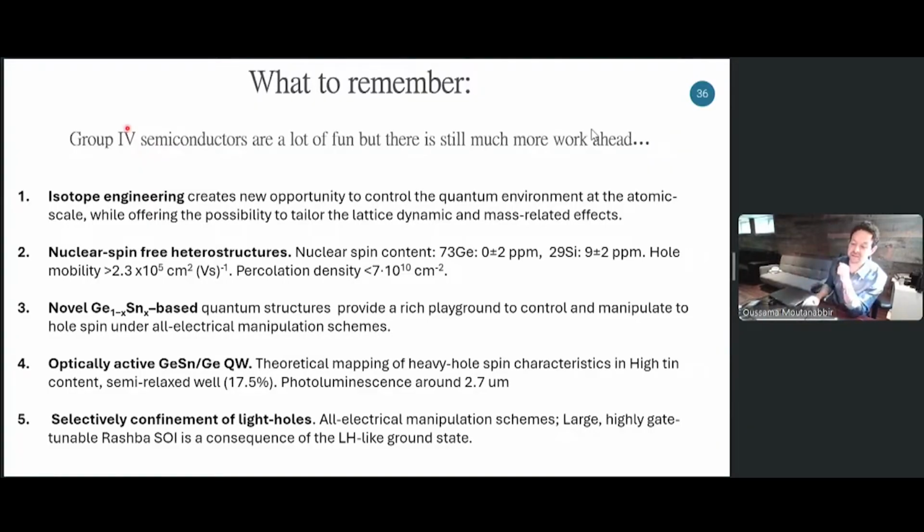But in germanium-tin, I think it will be extremely important to develop CMP, and CMP in this heterostructure would be extremely challenging. It's not that easy. Either you develop a very gentle CMP that can remove only a few tens or 100 nanometers, making sure that you get a better surface, but having a standard CMP from industry for germanium-tin is not going to work because the thickness of those layers is very low. So answering your question, for silicon germanium we didn't see any difference, but for germanium-tin we anticipate that CMP will be critical.